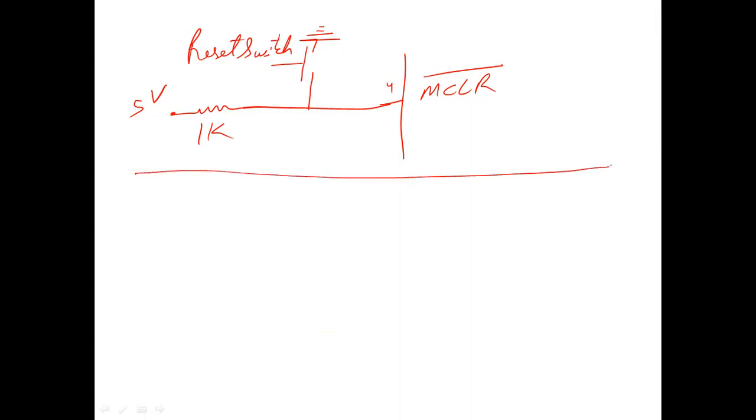Now let us look at programming a PIC, how you can program a PIC. So software is written and compiled using a personal computer and then downloaded to the microcontroller ROM as machine code. Now the assembly language used to program a PIC 16F84 consists of 35 commands. And this set of commands is called an instruction set. So there are 35 commands.